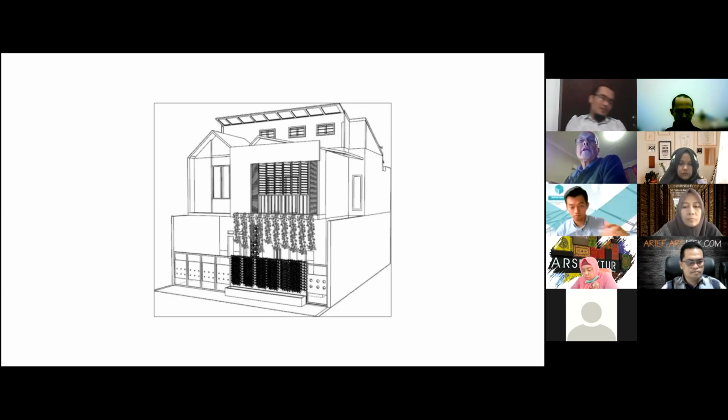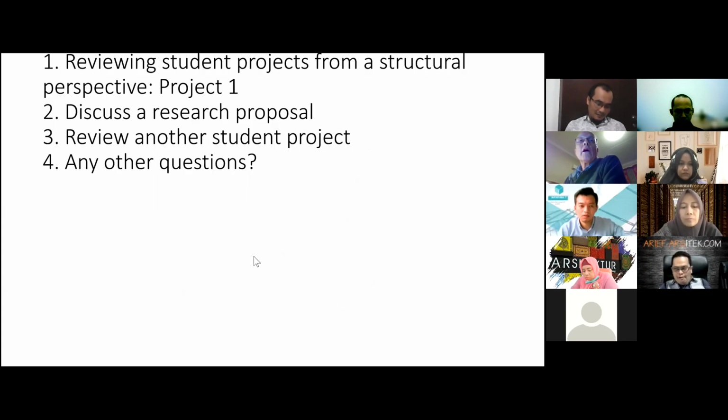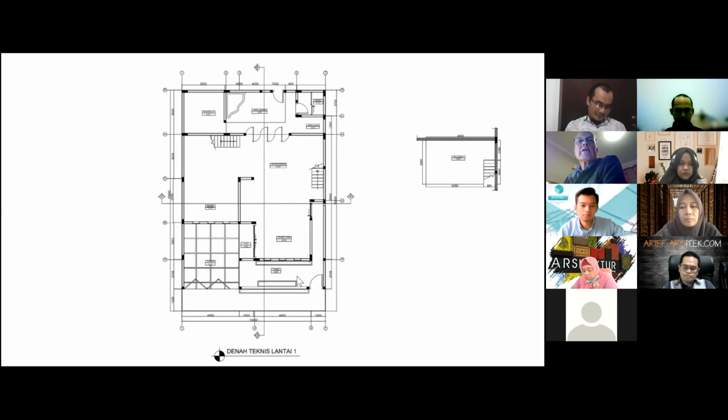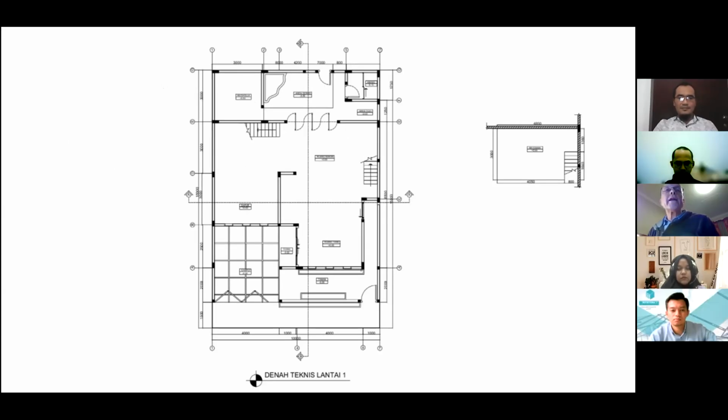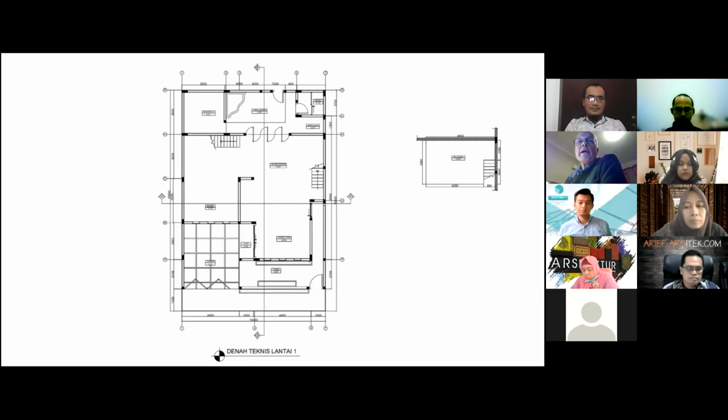And so what I suggest is that, going back to the floor plan, we put in, say, 1 or 2 moment frames at the front of the building and even at the back of the building. And that means that these walls here would just be infill walls. And we wouldn't be relying on confined masonry at all. So that is my suggestion.